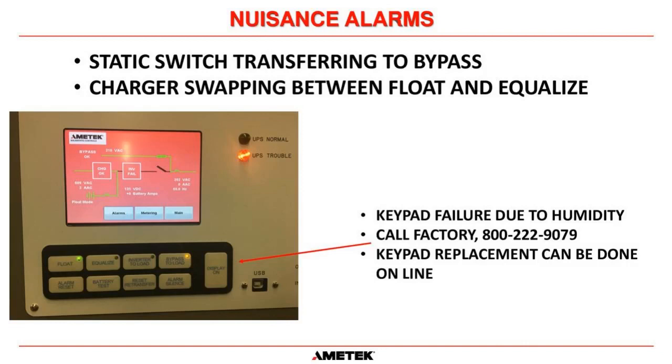And we're going, all right, what are these guys in the Gulf doing that nobody else is doing? Let's look and say, what is up with this? Finally, we concluded there was moisture getting in the keypad. After a little bit, we realized we could disable the keypad. Fortunately, the cable off the keypad slips right through the front of the door. It's a real thin cable that has a connector on it called zero insertion force, and it just slips right into its mating connector right there.